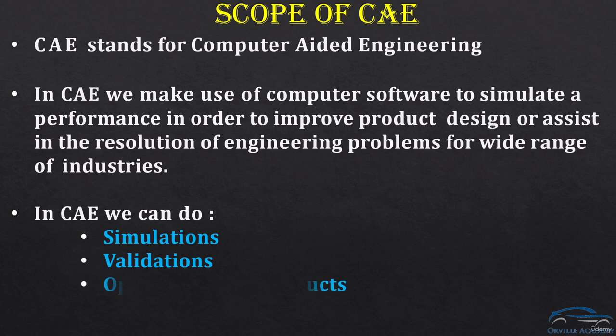The third and one of the important things that we can do in CAE is the optimization of a product. In recent years, more and more organizations are doing optimization. With optimization, we start with a very simple shape. For that shape, we apply some constraints in terms of how much load it has to sustain, how the stress distribution should be, what the frequency of the end product should be, and which manufacturing method we are going to employ. All these constraints we define. Once we define them and specify the design space, the software will give us the final design of the product.